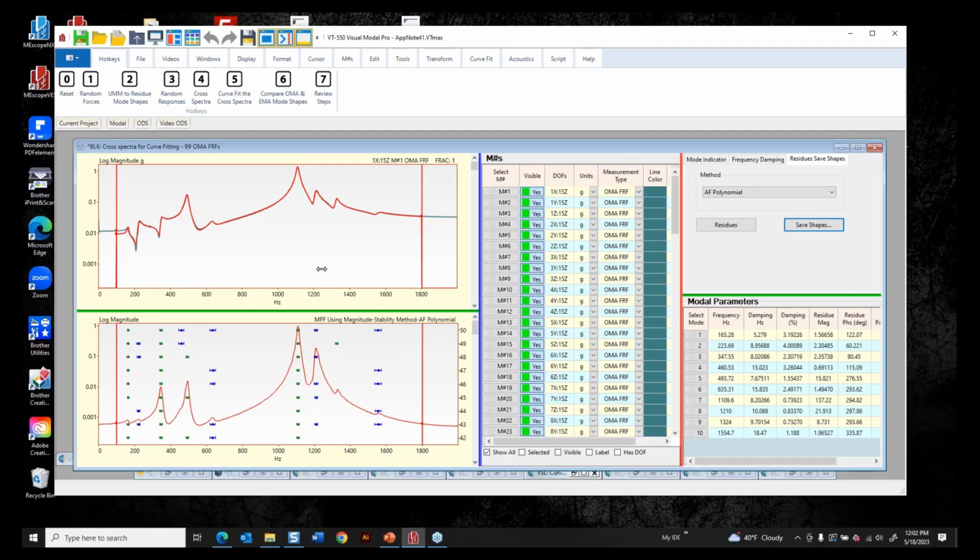Now we know in a rotating machine, the peaks only show up at the multiples of the running speed, but they can show up at other frequencies also because of excitation, gearbox, gear mesh. Those are typically all multiples of the running speed, but those could be other peaks that are not necessarily multiples, they're just resonances getting excited by random forces that we can't measure. So again, the best thing is to measure the forces, one or multiple. In the case of a hammer, we went through the first 2 curve fitting sessions where we just curve fit FRFs. This is where we can't measure the FRF.